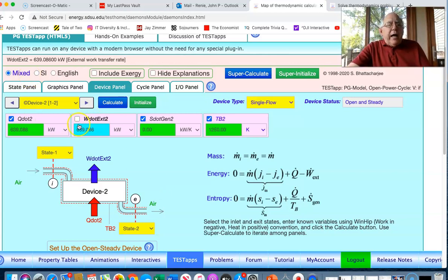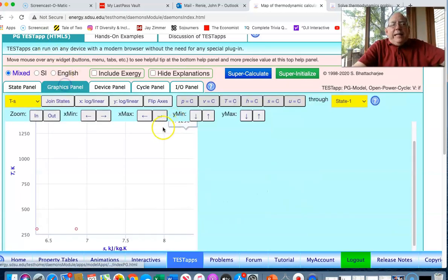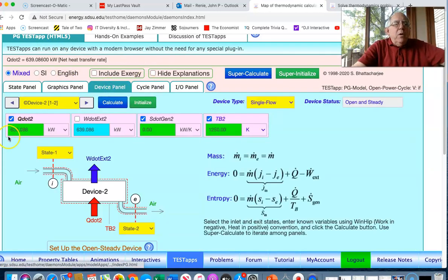Another way is that you can actually set this equal to this Q.2 and then it would calculate it. You could also put in the m dot, the flow rate, times the temperature times the difference in the entropy. You could actually put in the equation representing that heat transfer given by that area right there. So with that in mind, we now have the heat transfer that was rejected. We have the heat transfer that was added to the system.